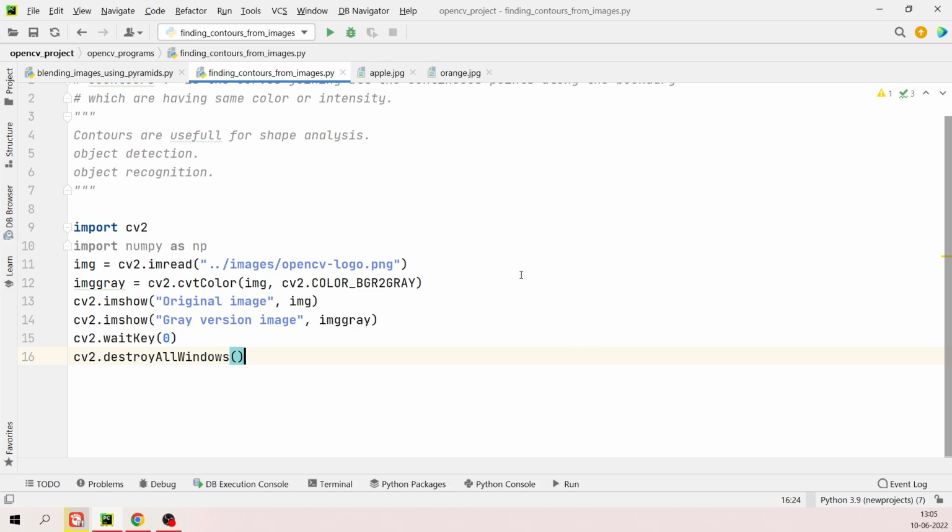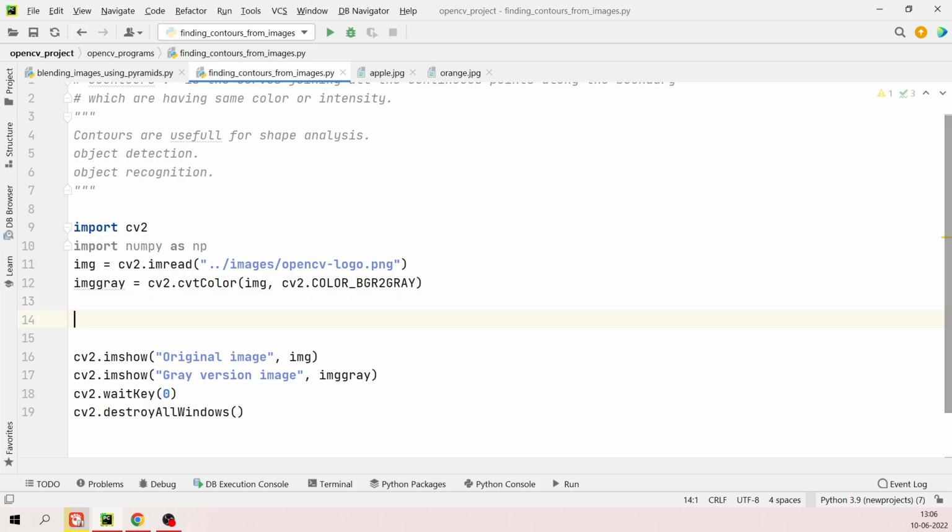But first, in order to find the contours, from this grayscale image you have to find the threshold level, whichever you are going to set. The image pixel values go from 0 to 255. But you need some kind of threshold level, for example taking about half of the points, from 127 till 255.